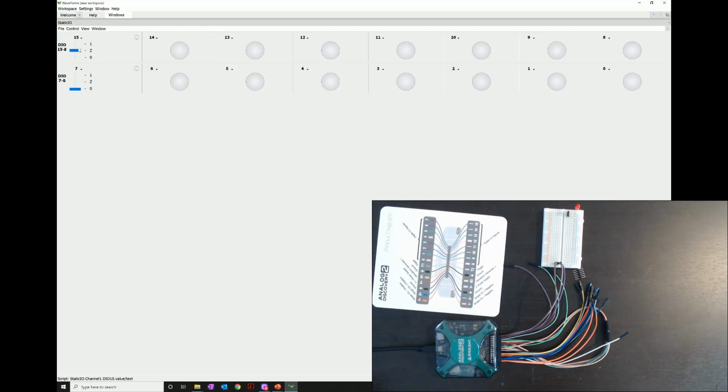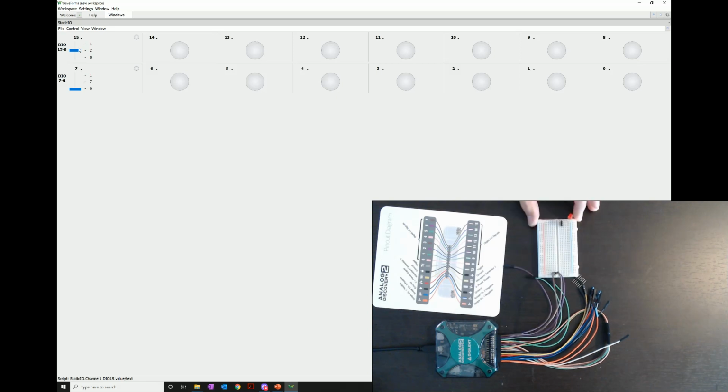We can also use the digital output to interact with hardware like a simple LED. As a quick reminder about LEDs, or light-emitting diodes, these are diodes that convert electrical current into optical power. What's relevant here is that these are diodes, and accordingly that polarity matters, meaning that current only flows in one direction through our LED. The LED has an anode and a cathode, and the LED turns on when our current flows from the anode to the cathode.